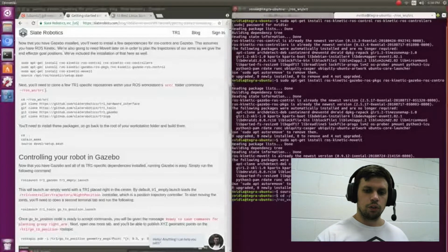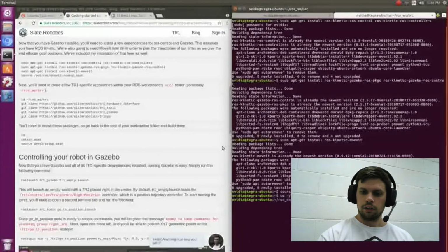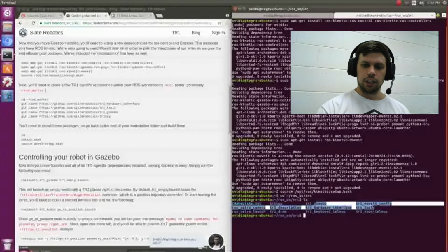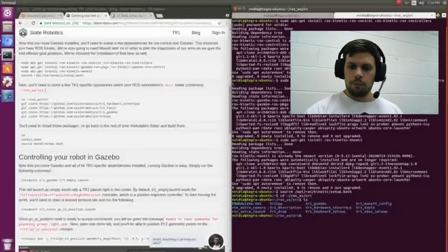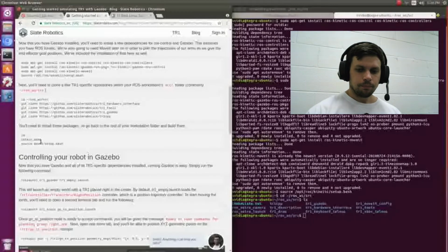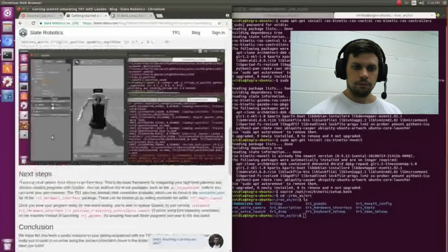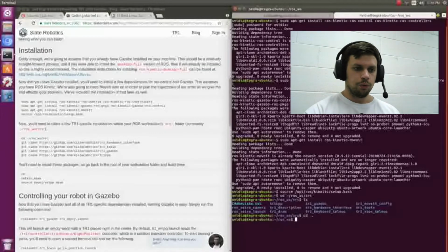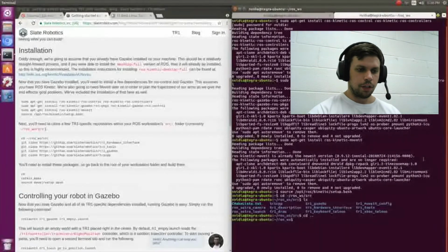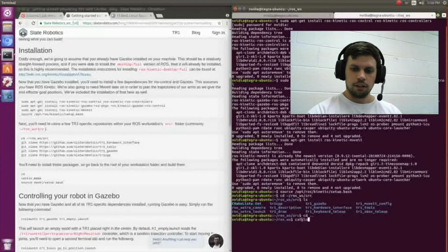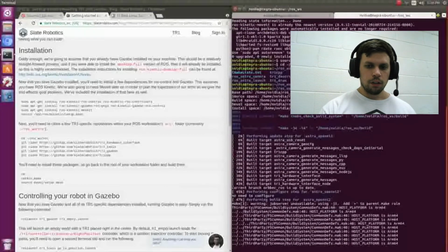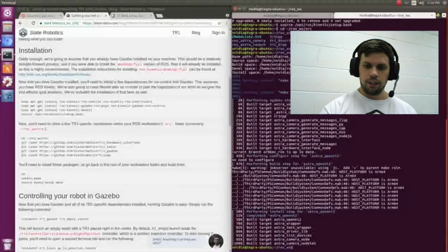You'll need to install, and look, I'll show what I have here. I have all of those packages and even a few more in my ROS workspace. So once you've done that, we will go back to the root folder of your ROS workspace, and we'll run catkin_make just to install everything, which I've gone ahead and done here.